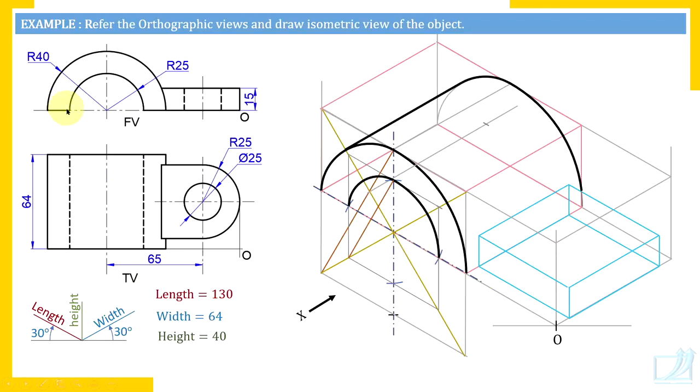Now you are going to draw these two edges to complete that semicircular strip, that is the front end of the semi-cylinder. Remember, a corner is formed by three edges. So from this corner there must be an edge. This is the front side and this semi-cylindrical slot runs from front to back, and therefore there are edges here. Front to back means parallel to width.